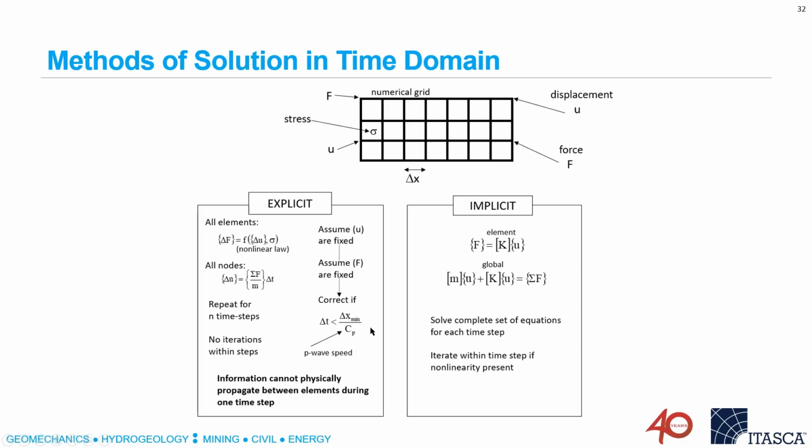The limitation of this particular method is one of not allowing the physical model to propagate faster than the wave speed in the solid. So this depends on the properties of the material. So typically these methods have fairly small time steps, but within each time step, all of the forces and stresses are satisfied.